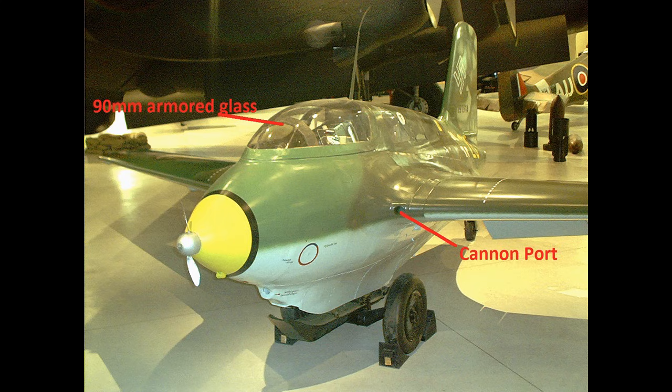Now, the mini propeller at the front drives an electrical generator. Behind the nose cone, you would find that generator, plus the plane's very small battery. It's about the size of a modern motorcycle battery, and it only had enough power to last a few minutes, hence the need for the generator. The nose cone incorporates 15mm armor, that's pretty thick, in more or less the location where you see the yellow paint here. The jettisonable landing gear dolly was unsprung.